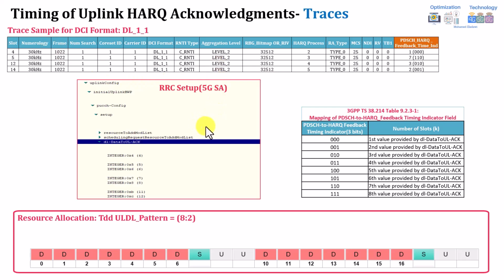So actually, this is mapped into a specific table. So this is how we're going to explain how the user will know the timing of the uplink. Assuming now in the bottom left figure here, you have some downlink transmission, and this is your frame. Your frame is working as A2 from the user perspective. So whenever the user receives, for example, data at slot 3 or 4 or 5, you need to know he's going to send the feedback here or here or here and so on.